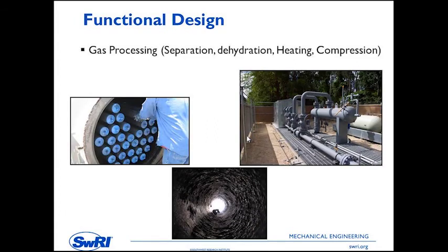Where are you going to locate your gas sampling points? How are you going to sample? Your sample probe should be installed in the middle third of the pipe, which is conventional practice. You want to install probes with heating to prevent condensation of liquids in your gas sample. And you want to insulate that installation so that you don't have any effects from wind or ambient conditions that would change phase.